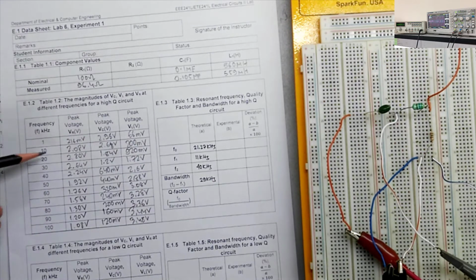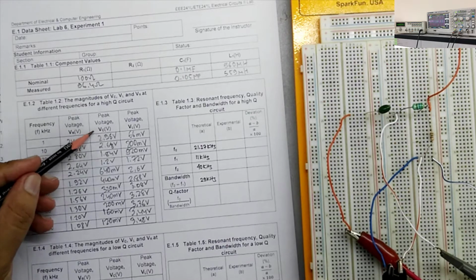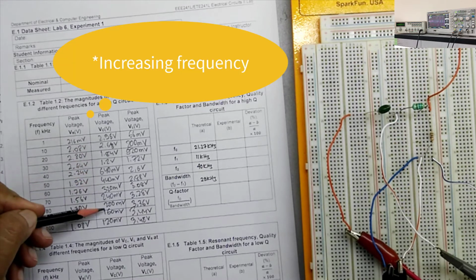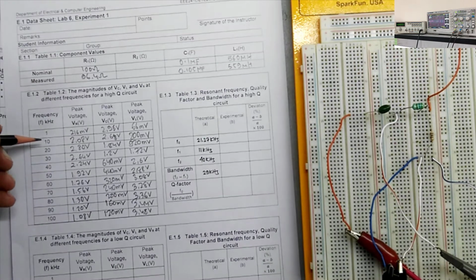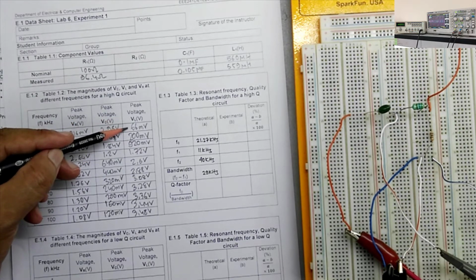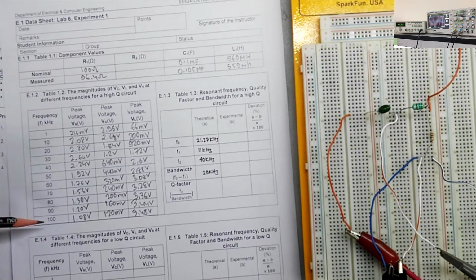So as we see, as frequency increases, the reactance of the capacitor will decrease, and that is reflected by the fact that the voltage drop across the capacitor is decreasing with increasing frequency. And when the frequency is increased, the reactance of an inductor will increase, and that is reflected by the fact that the voltage drop across the inductor increases as frequency increases.